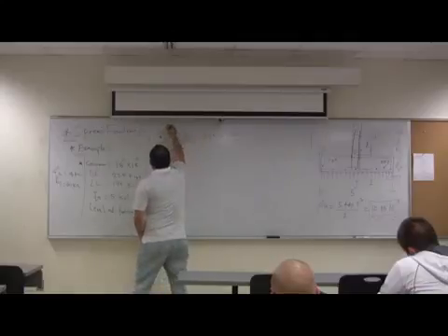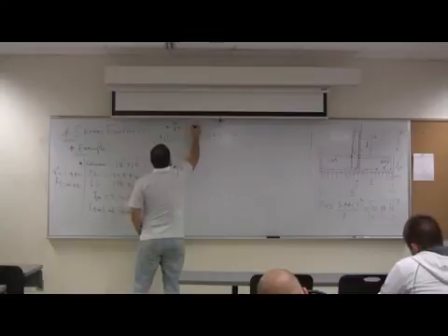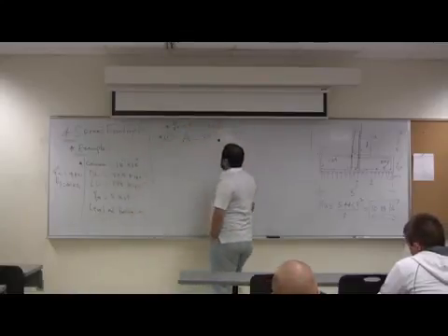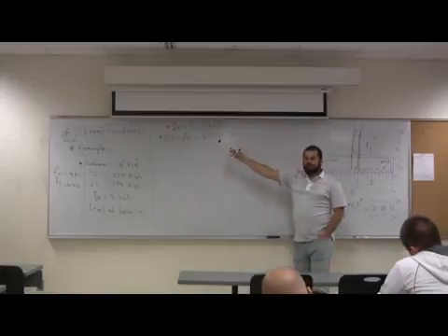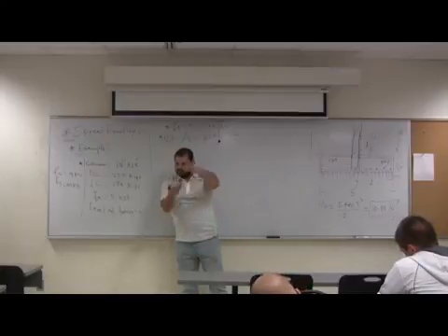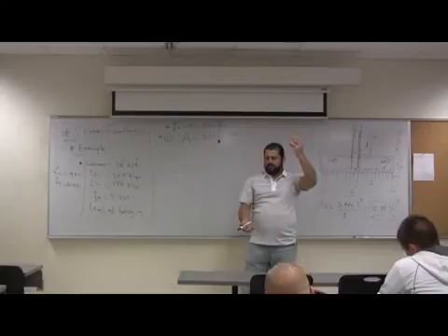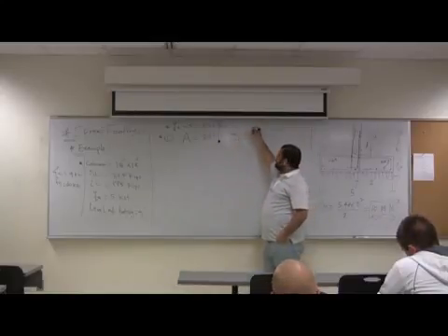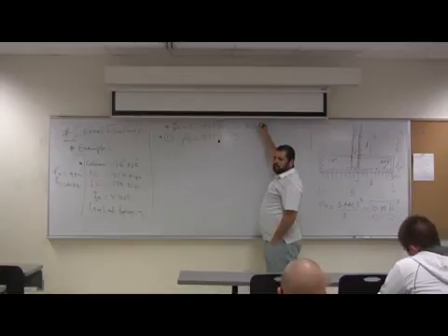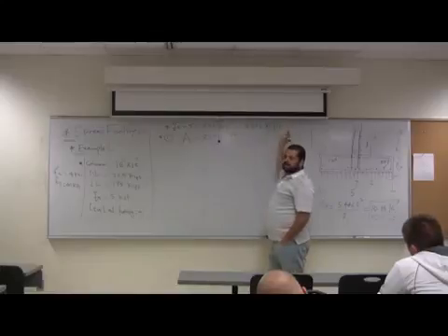Even before we do that, Q effective equal 5 minus 5 times 0.125. Q effective will be 5 minus 5 feet of average concrete and soil. Take it 0.125, as I said. So how much the top one? 4.375, yeah? Kip per foot square or KSF.